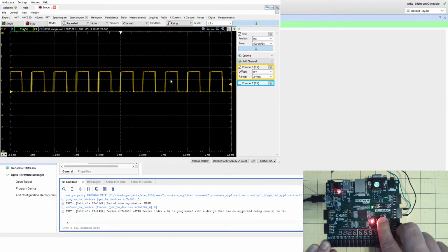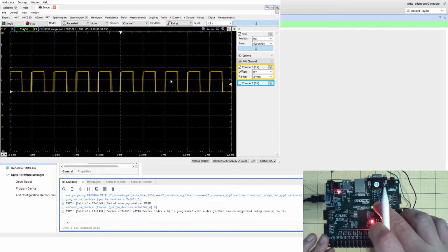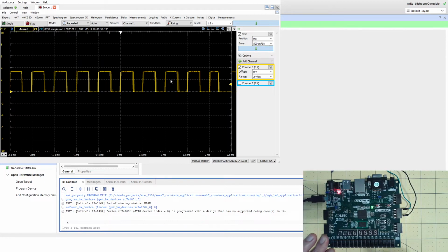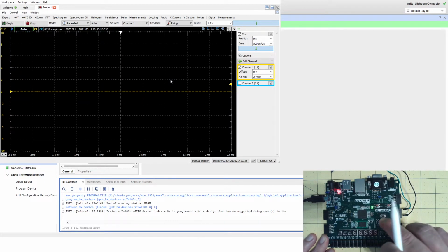Okay, so now what if I want to add the blue color? So I'm not outputting the blue color on the PMOD headers. But I can definitely control it because my circuit allows me the red, the blue, and the green. Let's do the green for now. The green is when I do 1. So this is at 1. Now whatever intensity I put in here will be set for that green. Frankly speaking, I'm going to reset it so everything is at 0, so that you get to see that it's actually setting up the green color. And you can see in here it's now the green color.